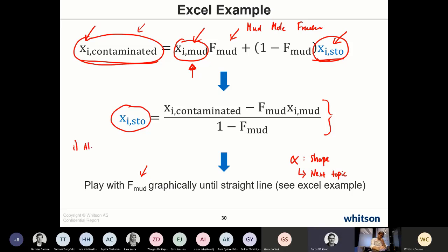B, the answer to the question is that if you have lab PVT data on contaminated samples, you have to have an EOS that contains the oil-based mud components, and you can do the EOS tuning with that data. If you have PVT, you have it.